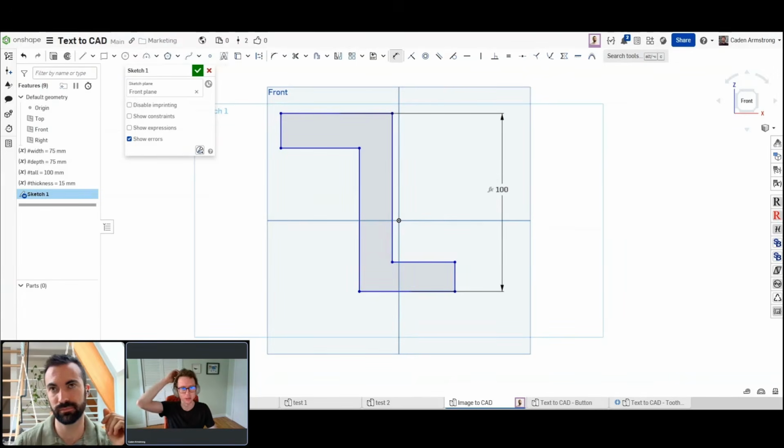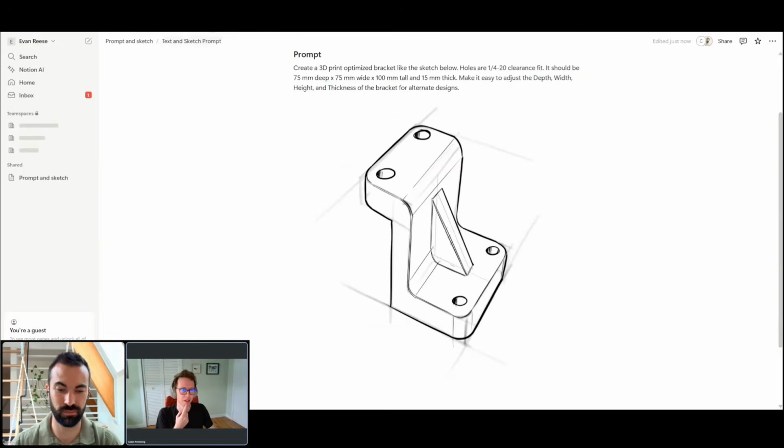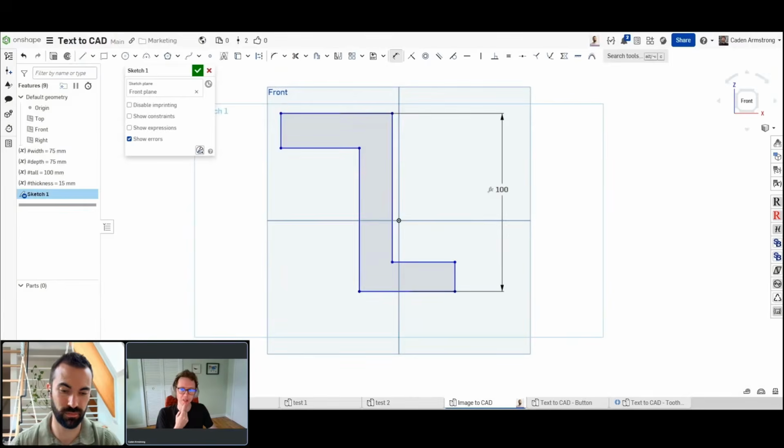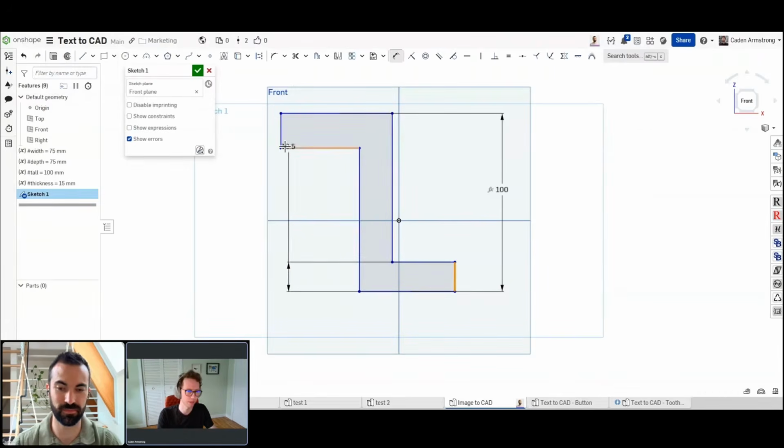Oh, you got holes. The challenge is that even me as a person who's 3D printed and failed, I know if you put a hole sideways, then you have overhang. But we also have this overhang as well. So we've overhanged in two directions, or potentially three with the rib. So that's a challenge. I'm curious if an AI with more experience would be better at that.